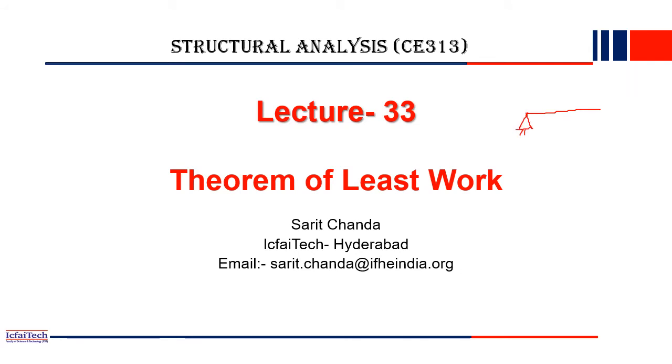Here is a simply supported beam. One end is a hinge, another end is a roller. If a single load is acting, maybe a point load, or maybe a UDL, or maybe half of the span has a UDL, then it is a simple loading condition. Using the geometric method, we can easily solve it.